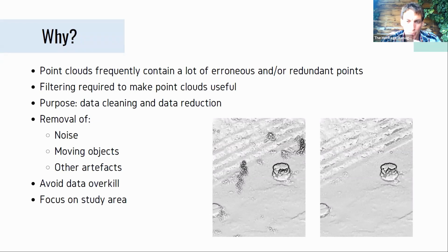Also, if you would go back, for example, to the point cloud that was measured of Syntagma Square in Nafplio, in that case, we are measuring in the middle of the day, so people are having their coffees at the terrace, they are walking for shopping, you have tourists walking around. So all these objects are not useful in the point clouds. They are erroneous or redundant points that have to be removed.